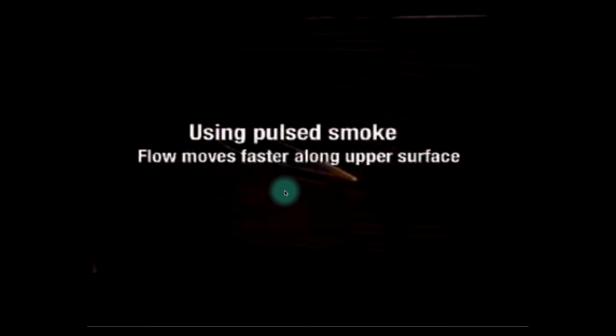Okay, so the point of an airfoil is to generate lift, right? And we know from what we've studied in the course so far, we're going to have an energy balance in these flows. So that means that if you're capable of making a flow go faster or have a higher velocity, you're going to be able to decrease the pressure. So higher velocity, lower pressure, right? So what we're going to see on an airfoil is as the air comes in over the top of the airfoil, it's going to go faster, meaning you have a lower pressure, and the air is going to slow down on the bottom of the airfoil, right?